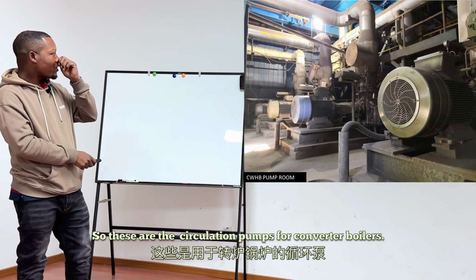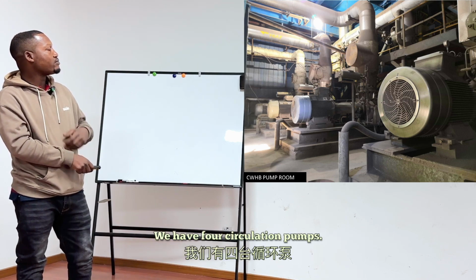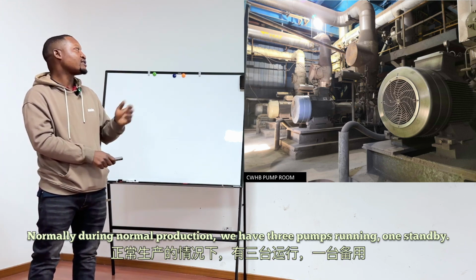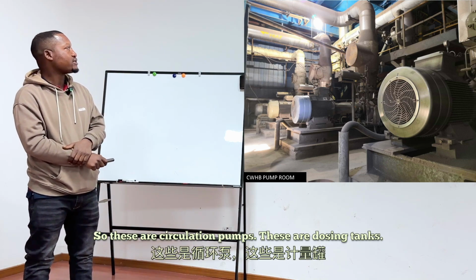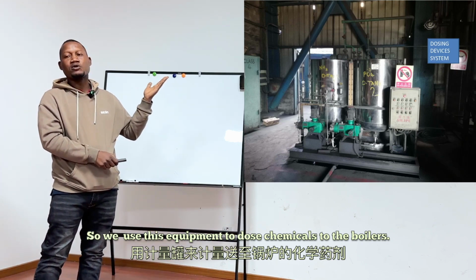These are the circulation pumps for the converter boilers. We have 4 circulation pumps. Normally, during normal production, we have 3 pumps running, 1 standby. These are the dosing tanks. We use this equipment to dose chemicals to the boilers.